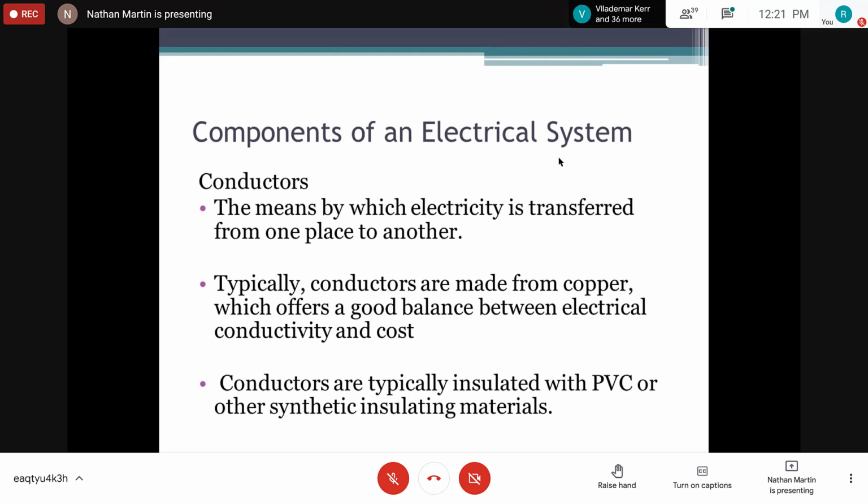So if you were to operate a 75-degree cable at 90 degrees, and these are in Celsius, then it will start to degrade at a much higher rate, right? And this is why, when we're talking about overloading the cables, remember when you pass a current through a conductor, it will produce heat, right? And if we're passing more than the maximum allowable current through that conductor, then the insulation will start to break down, all right? Because it's designed to work at a particular temperature.